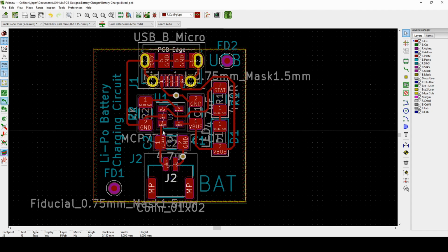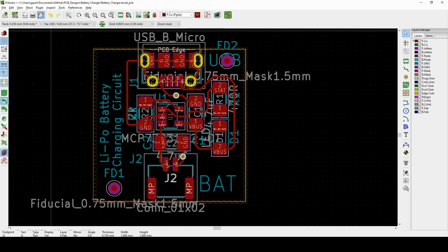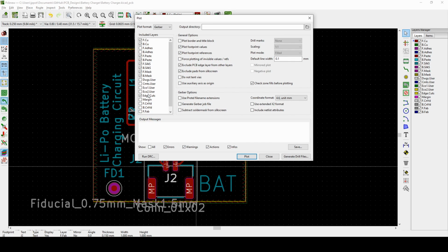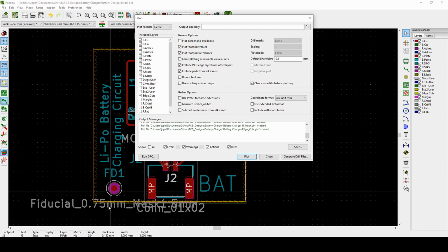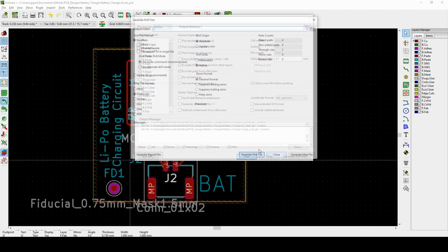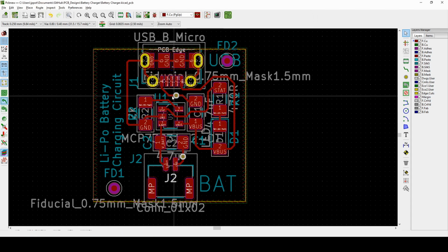We have already made a video about how to generate the Gerbers and things, so we won't go too much into that detail, but basically you just push plot. You can generate the Gerbers here, and first refill the zones because we added fiducials. They want us to refill it. Plot is the button, and then remember to generate the drill holes. The vias and things like that are all drill holes, and these are drill holes. So we've got the Gerber sorted.